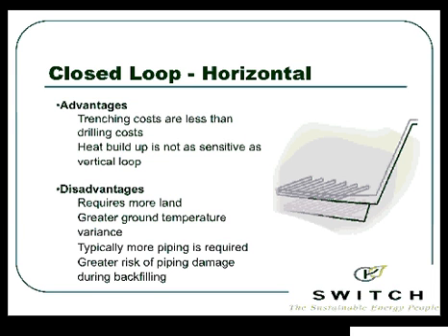George is here, you buy your ductwork, 4-inch, 5-inch, 6-inch round ductwork. It depends on when they built the house, and whether they tried to cost save and downsize that ductwork. Now it's going to be too restrictive when I put that heat pump on, because I want to move more air through there. I can put a blower on there that'll push it through, but if we move it faster, then we're going to have noise.